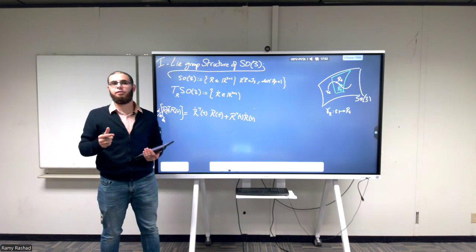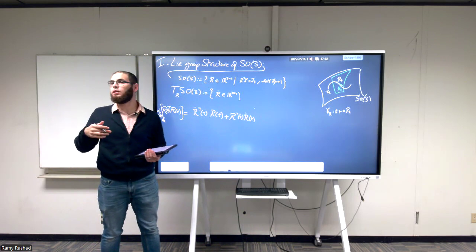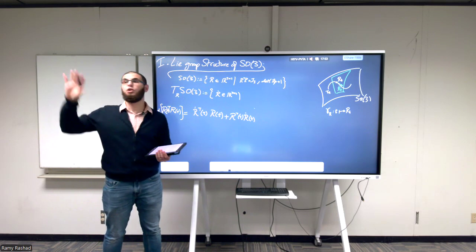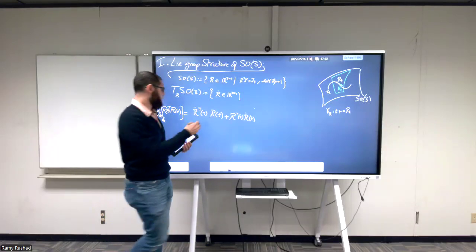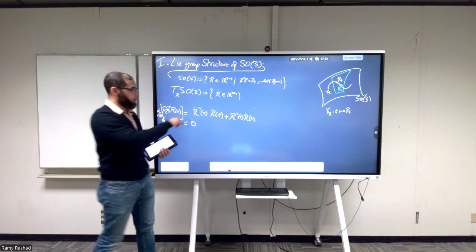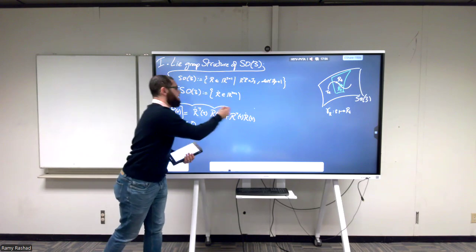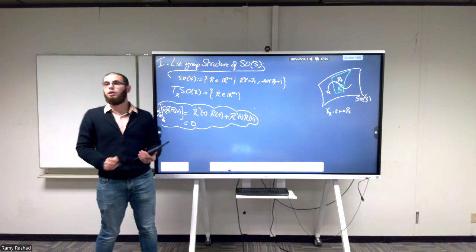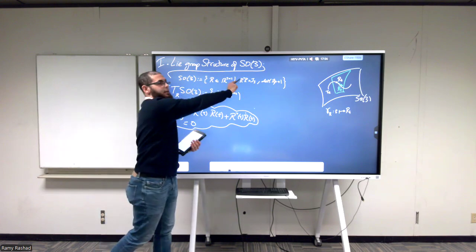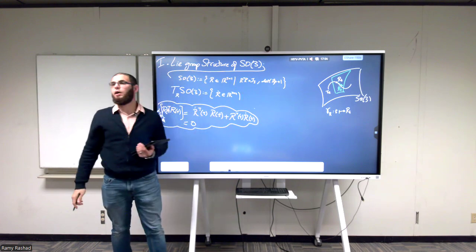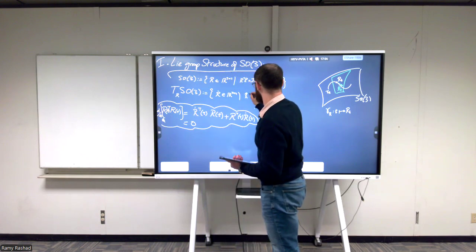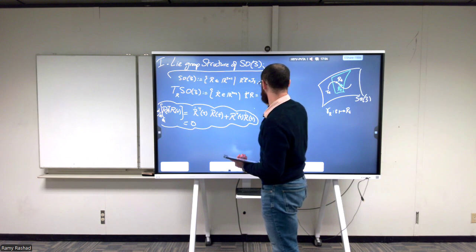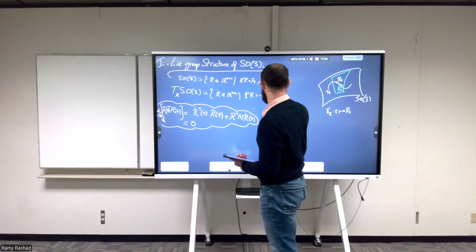What's the differentiation of the identity matrix equal to? Equal to 0, the 0 matrix, right? Because the identity matrix is a constant. So if I differentiate all of its elements with respect to time, I get 0. So this is in the end equal to 0. In other words, what you see here is precisely this idea of the compatibility between R dot and R. If R has to satisfy this constraint, then R dot needs to satisfy this constraint. And this constraint simply says the following. R dot transpose R is equal to minus R transpose R dot.